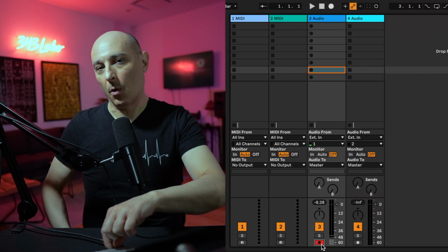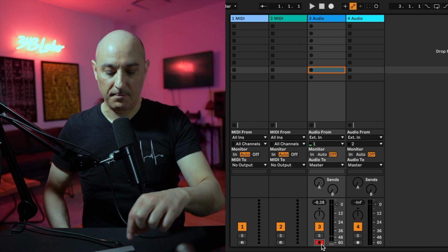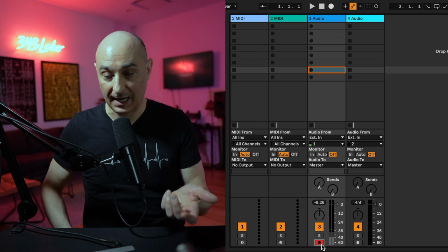Now, at the preamp, I need to make sure I'm not bringing that in too hot because I could distort or clip at the preamp. So in this case, it's pretty low level. If I look in the DAW, if I have it record armed, I can just keep turning this up until I actually have a good signal.